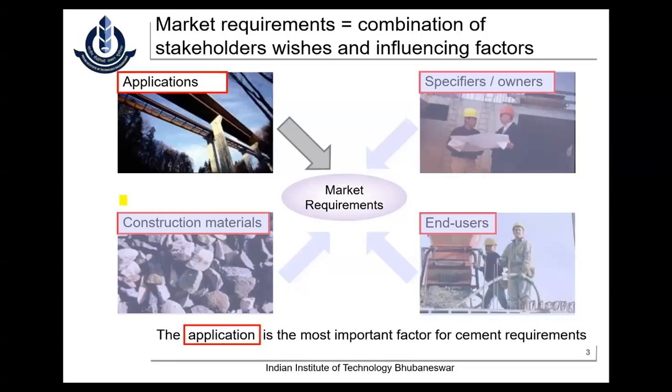When you are finalizing any product for a particular application, for a particular project, the cement has to be tested. No matter that you test the individual cement as per the requirements, it has to be a proven product in the concrete. Okay. Nowadays, people have gone beyond the strength-based design. We are talking about durability-based design, and performance-based specifications have come. Like you rightly mentioned, you're using this concrete for a particular application.